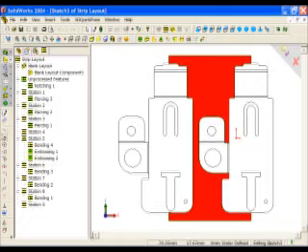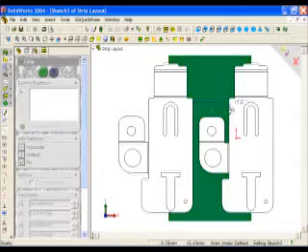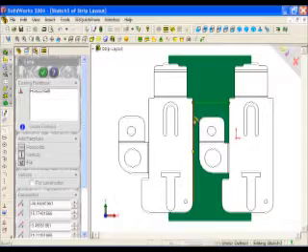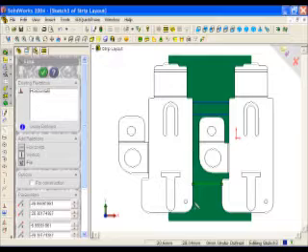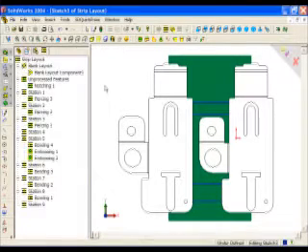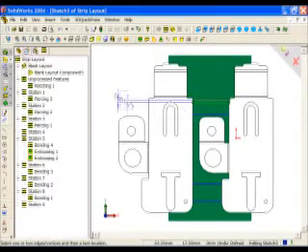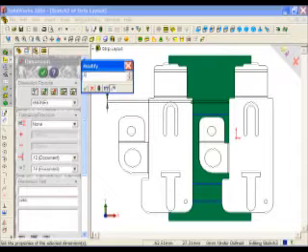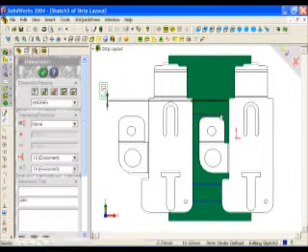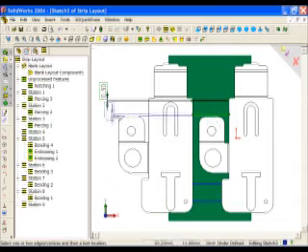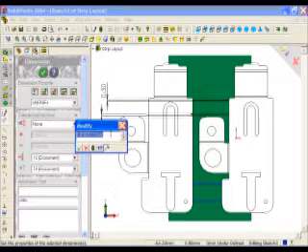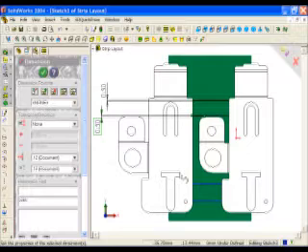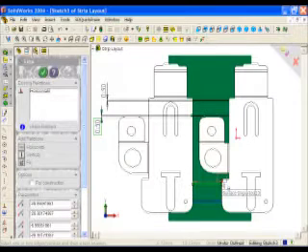Go back to that view, draw some carrier lines in. This is standard SolidWorks sketching tools. And we can throw some dimensions in to be a little bit more accurate. Once again, going back to here, let's pick up that edge. Let's make that 0.5. Looks good. Go to that edge, to that edge, 0.5, and very similar here.